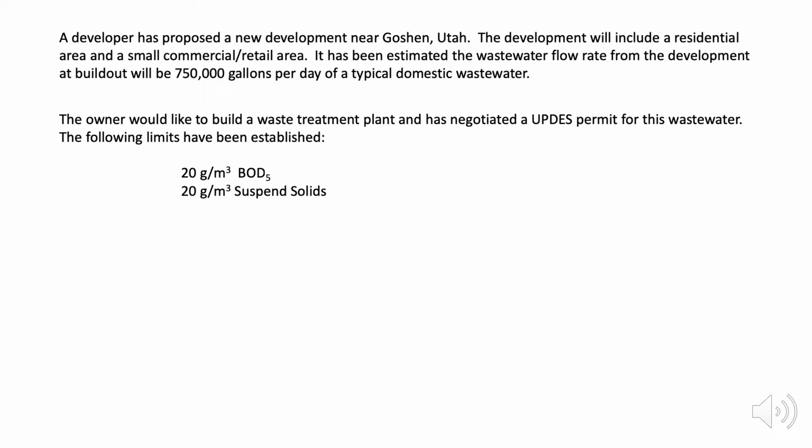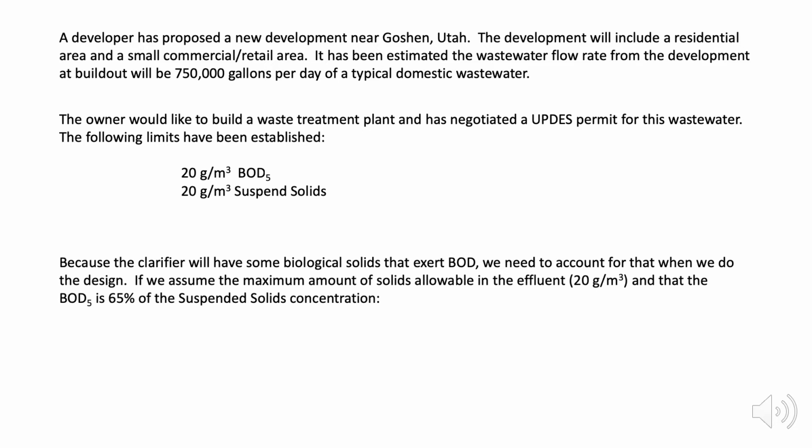So they went to the Department of Environmental Quality at the state and applied for a UPDES permit, and after some negotiations, the limits that they receive for their permit are listed here, where you can see that they need to have no more than 20 grams per cubic meter of BOD5 and no more than 20 grams per cubic meter of suspended solids at their treatment plant.